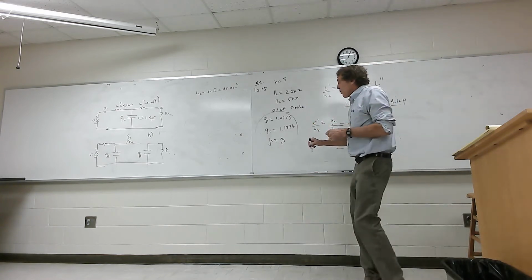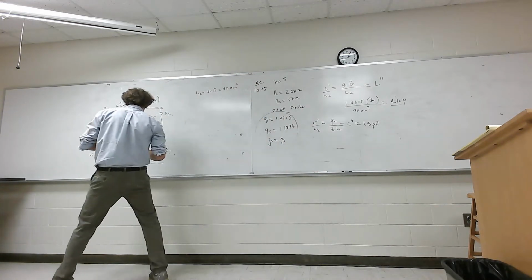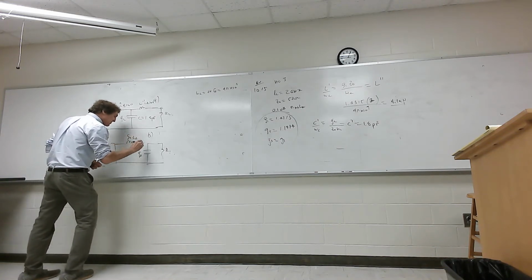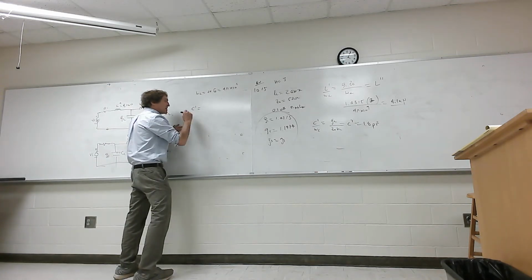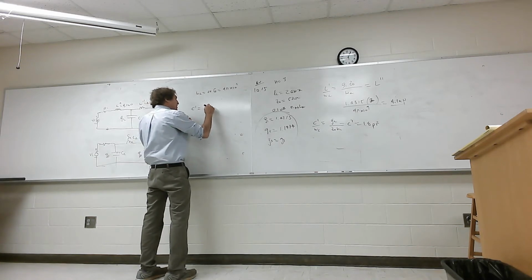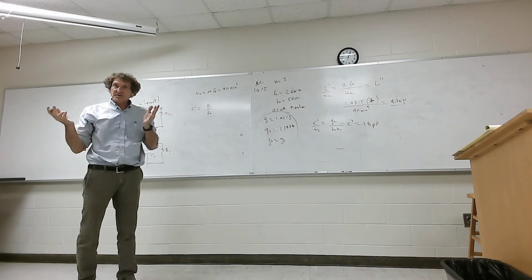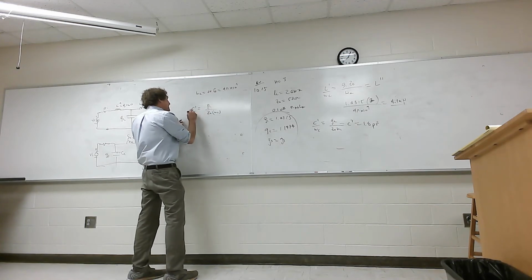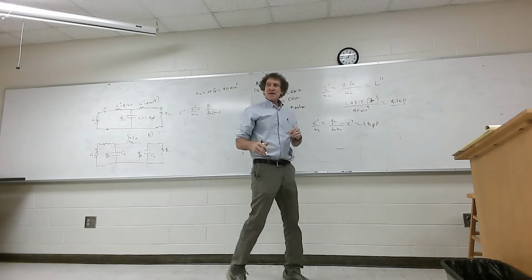All right, so now, over here, since G1 right there is associated with a capacitor, to get the value of this capacitance, I'll just call this C2, and I'll call this L2 and C2. To get this capacitor, first we take C prime, and that's going to be G1, and it's going to be divided by Z0, because it's a capacitor. Y'all follow me on this? Capacitor divided by Z0. Then you're going to divide that by omega C, and that gives you the value of C double prime.